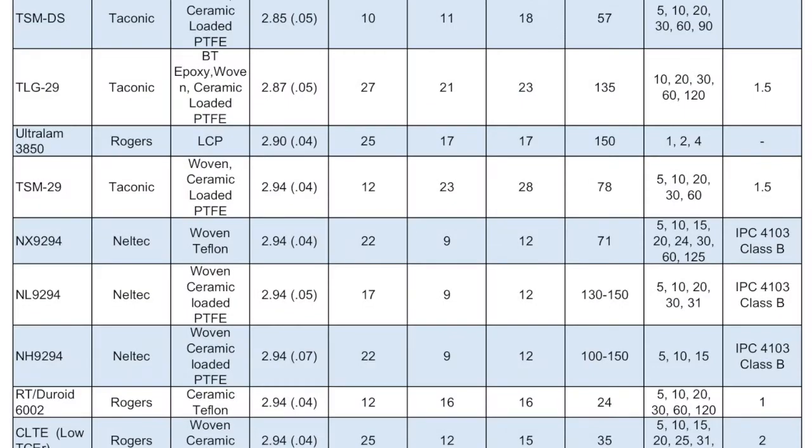With the increased usage of conventional low loss thermosetting resin systems, and I call them conventional because they're not like the thermoplastics of PTFE materials, the PPO, PPEs, and the hydrocarbon materials, we're now starting to approach those loss levels. And so you see these more traditionally fabricated materials being utilized into frequency ranges in the 10, 20 gigahertz range.